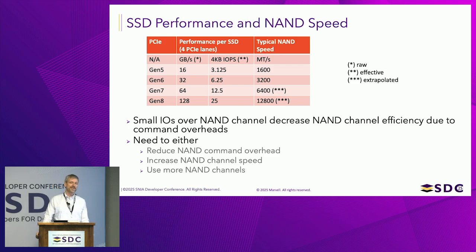And that, of course, is a challenge on the PCIe side, but also on the NAND side, to develop these high-speed NAND interfaces, from a signal integrity perspective, but also from a power perspective, because you have analog circuits on the interface side, and the power doesn't scale as well as with digital circuits.